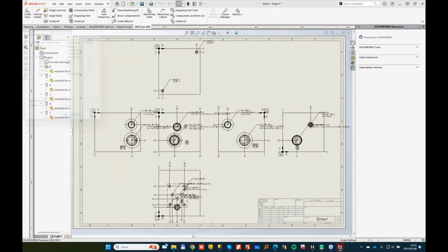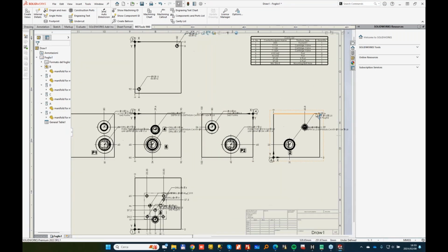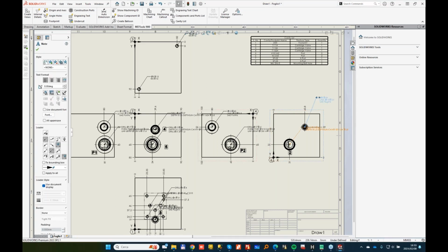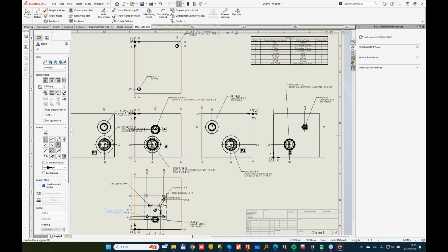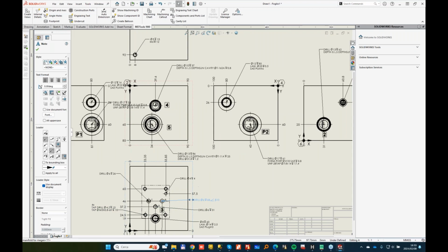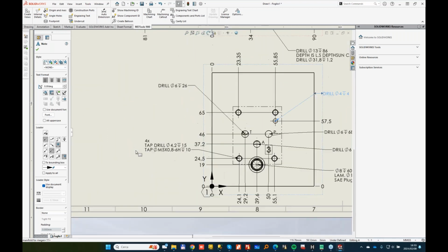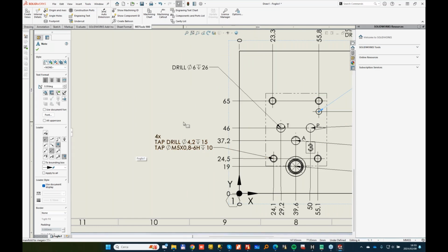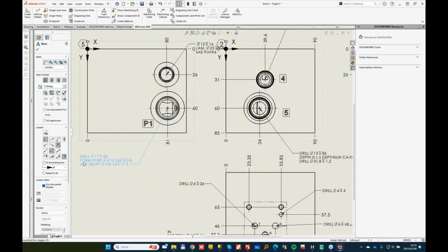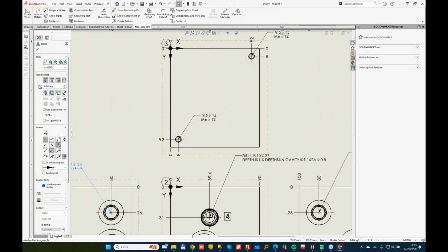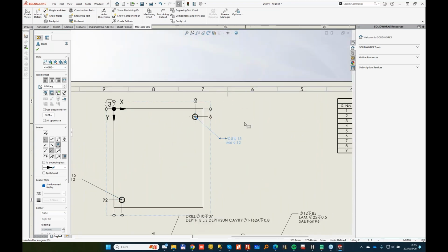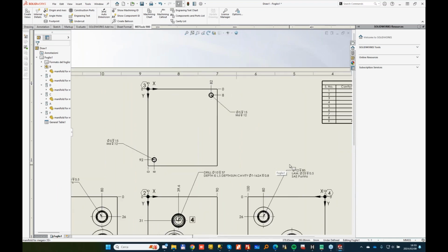So with my cavity list, I'll place it in the drawing. And I'm just good to go. I just need to relocate all the machining callouts in order to help readability of the drawing. With the latest version of MDTools, we are also grouping identical operations in the same footprint. So in this case, it's describing 4 times the M5 bolt holes for the NG6 valve. And it is possible to group identical callouts. But I think we are good.